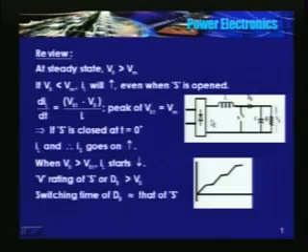Okay. What about the switching times? When I close the switch, diode should stop conducting and immediately the current should start flowing through S. And when I open the switch S, immediately diode DB should turn on. Otherwise, we are breaking an inductive circuit, because you open the switch, diode is taking its own time to turn on. So momentarily you are breaking an inductive circuit. So there will be a spike and maybe a device may fail.